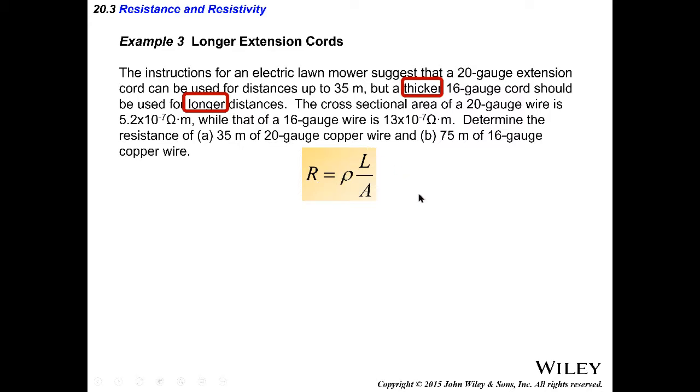All right. And you want to have the resistance less so that there is no potential for energy loss, number one. Number two, there can be issues with your rug. If I have a fancy living room, and I have a carpet, and now I just anyhow plug in an extension cord where the cord is very thin. What happens is that the resistance of that extension cord then is higher.